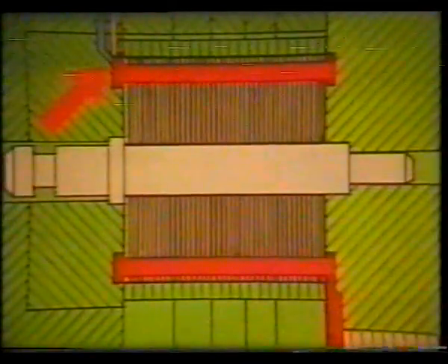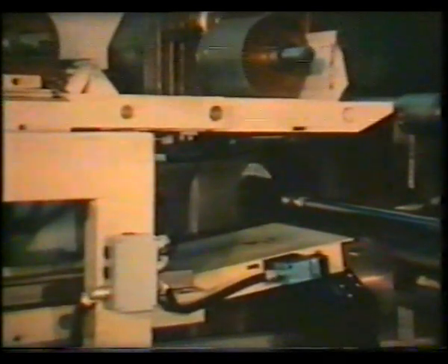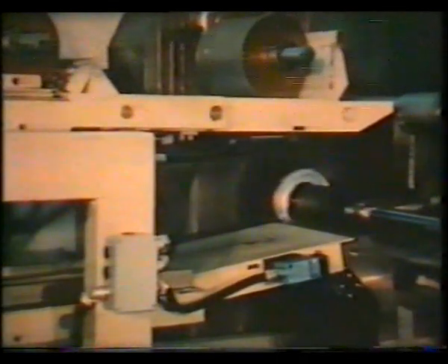This diagram shows the filling process of the die, during which the Buhler die vent control system prevents the occlusion of air in the casting. Here, the displaced air escapes through the vent valve. On solidification, the rotor is returned to the loading station. The ejection stroke through the trimming die removes the runner, and the transport rod carries the rotor back to the prism.